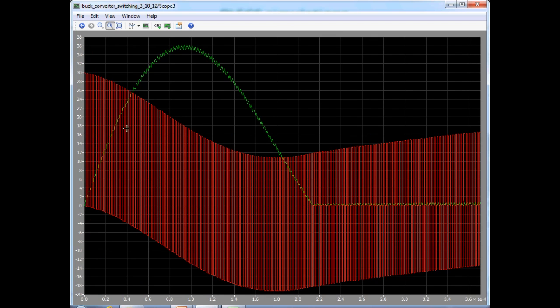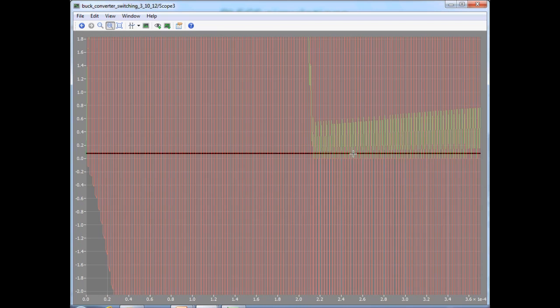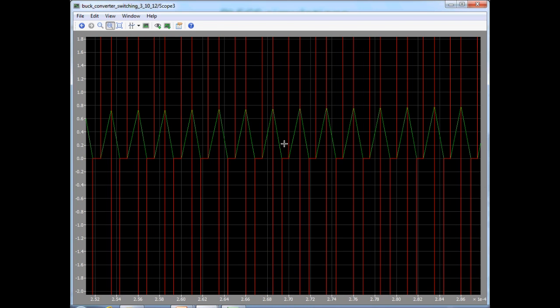So if you look at here, after these LC oscillations, eventually it is tending to go to the steady state. Notice that in between it has also gone into DCM mode. You can see the inductor current was rising during the on interval, falling during the off interval, and for a small period it remains zero. It is neither rising nor falling, and that corresponds to the DCM mode of operation.